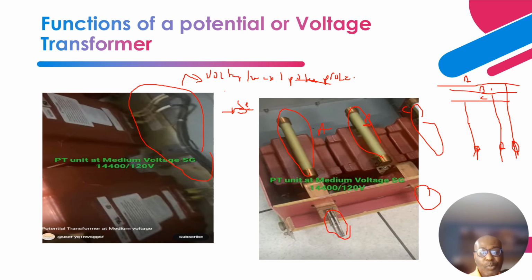Okay. So this is what energizes this PT, right, in each phase over here. Okay, then it goes through a fuse, right? Remember, you need fusing to protect the circuit. So A, B, C, right? Then there's a clip below that goes to, so that's the clip that you saw on the previous slide. It goes inside the PT and it gets connected to the high voltage winding.